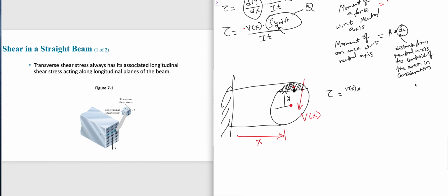Then what I'm asking you is, this would be, let's give a different name, y tilde, because we get confused between y and y tilde. So the shear force times this y tilde, that means you have y tilde times whatever this area is. Let's call this area above y: A of y is the area above y, over the moment of inertia of the cross section times thickness.